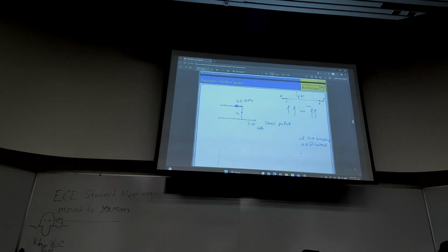We learned that already. If bending is not pure, what does that mean? Like eccentric loading that we're talking about here. Eccentric axial force. Again, force with an offset. The force is in here, but there's an offset to the cross section of interest at C. Then the neutral axis gets offset from the centroid. So keep these in mind.